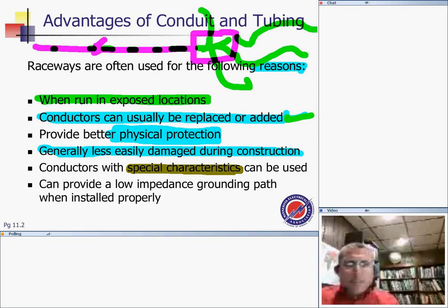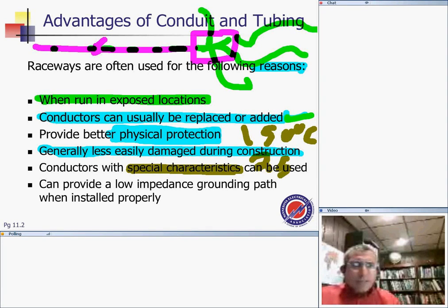How many of you have used high temperature rated conductors, like 150, for special applications? If you have a high temperature location, a very hot environment, the cables can get very hot. So instead of a 90 degree rated cable, you can use a 150 degree rated cable, and these are Celsius, by the way, and I think they can even go to 300. These conductors are easy to pull right through rigid or EMT conduits.